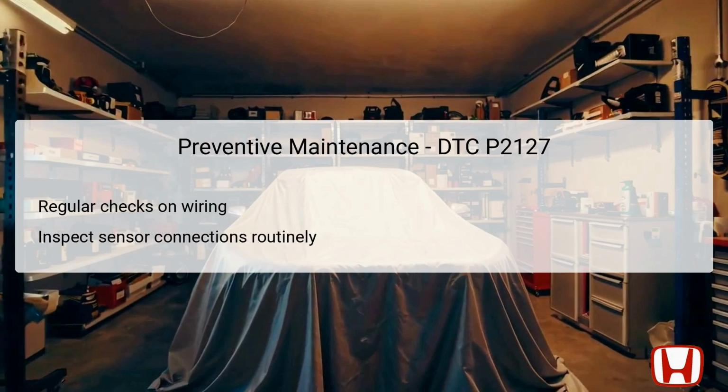Preventive maintenance is a key aspect of vehicle ownership, particularly regarding electrical components such as the APP sensor. Regularly checking the wiring integrity and connections associated with the APP sensor can help mitigate future issues, such as the one signaled by DTC P2127.